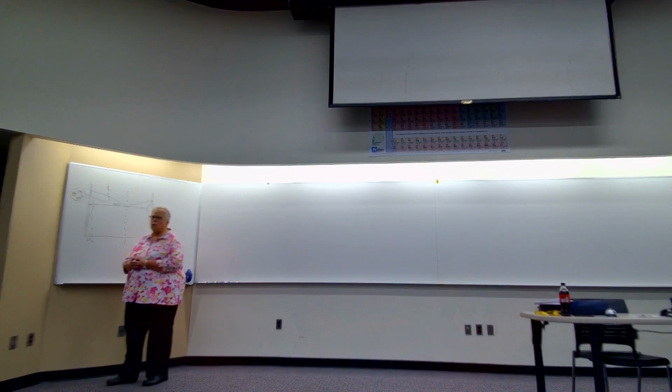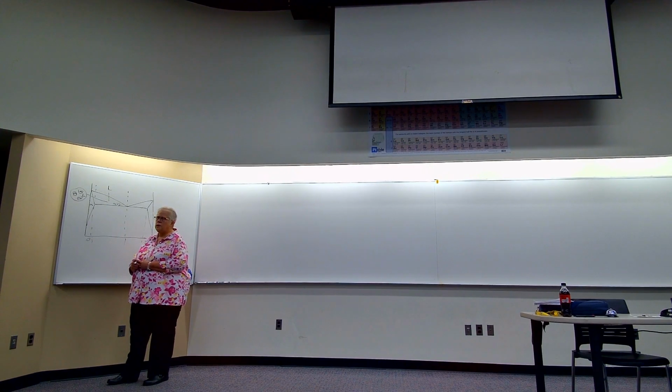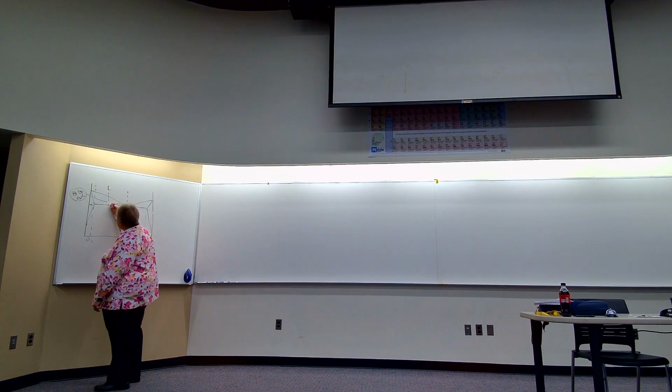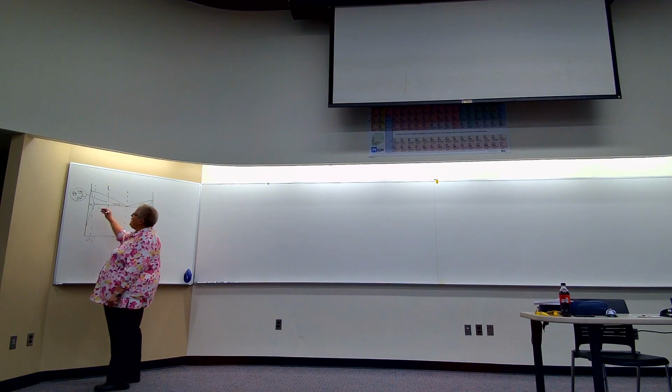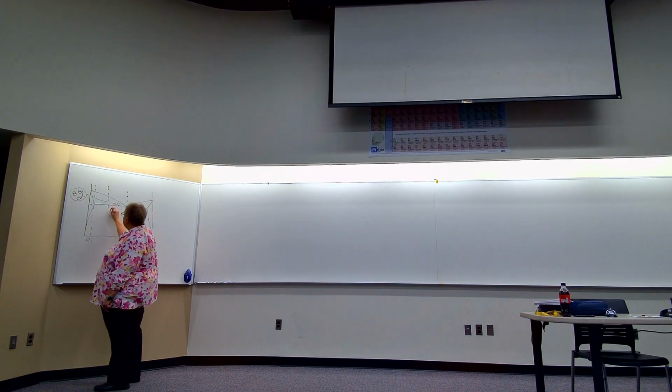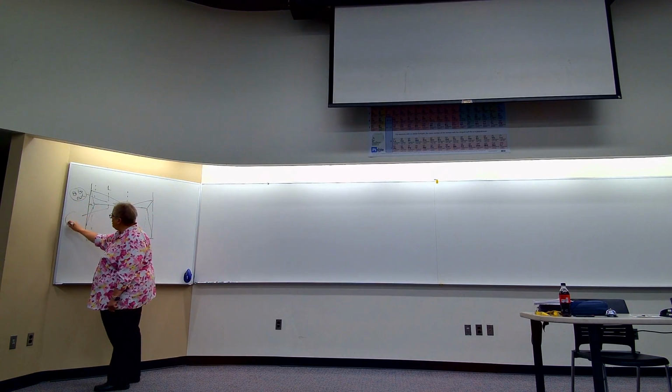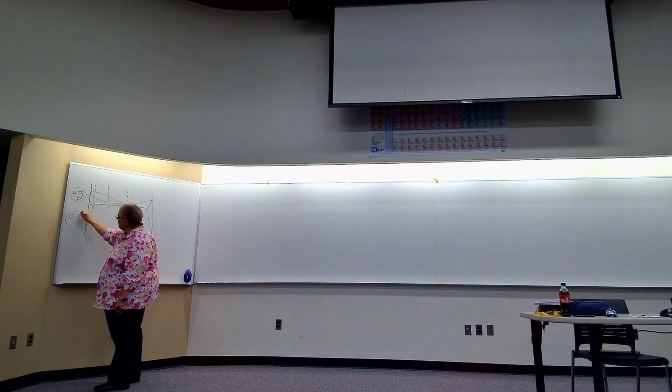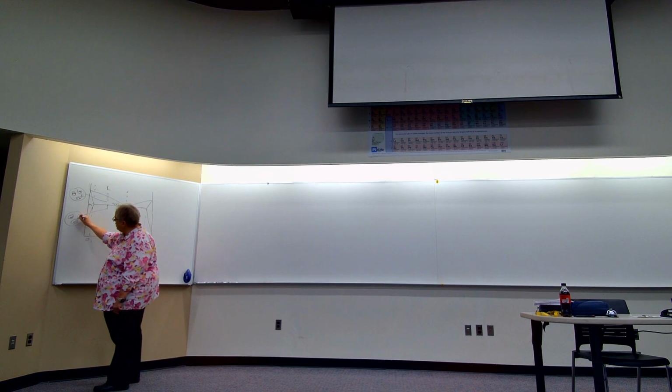Pro, before eutectic. And then when I cross here, anything that was liquid becomes eutectic. So I still have these areas of alpha, but where there was liquid, there's eutectic. There's this alternating layers of alpha and beta, right?